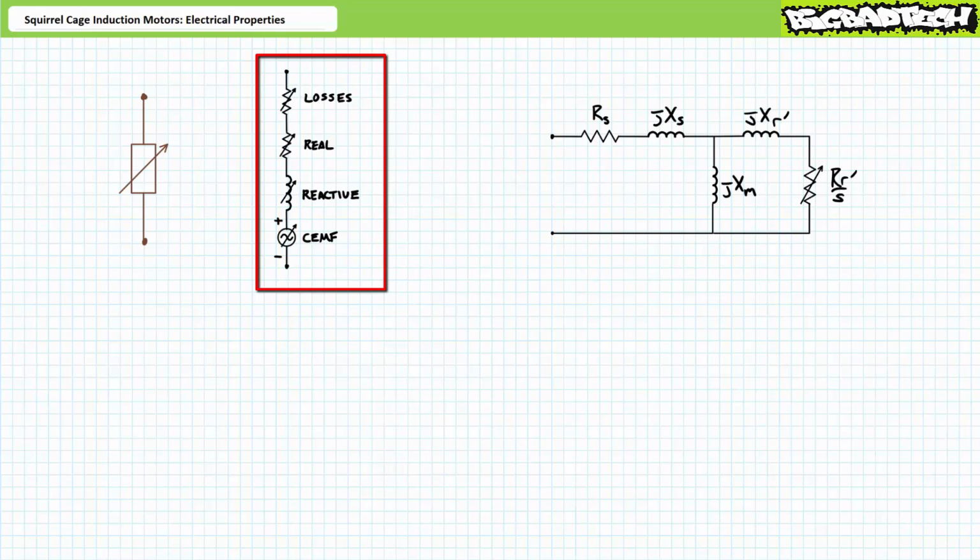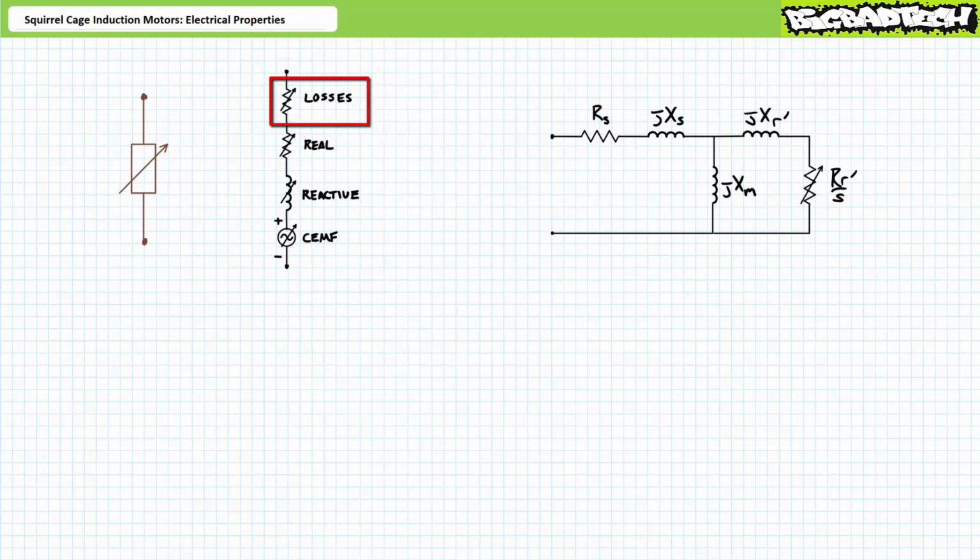Windings are not composed of variable resistors, variable inductors, and variable voltage sources. They're just windings. These are just imagined elements accounting for various effects. The elements inside the model of choice include a small variable resistance, which is meant to represent the losses inherent in the motor's operation. This could be resistance losses, core losses, sound losses, windage losses, bearing losses, or anything else that doesn't go towards real usable actual output. Any power consumed by this component would be considered a loss. I'd like to say this component is small enough that you could ignore it, but it isn't and you can't.